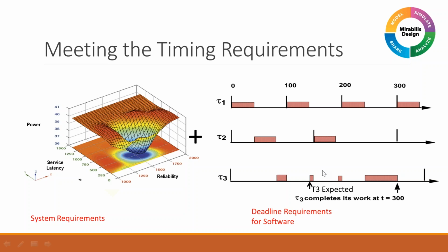So latency here, for example, I expected T3 to complete over here, but then it really completed over here. The reason being is I've got two higher priority tasks, T1 and T2. Remember, we set the priority. High priority tasks are preventing T3 from completing. So it gets preempted here, gets preempted here again, and finally it completes right over here.